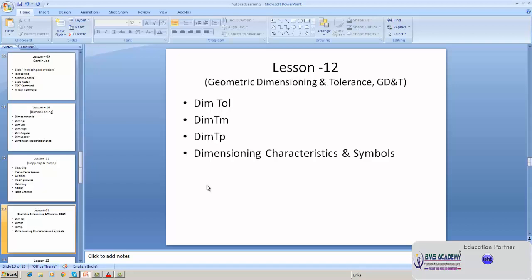design machines. It is necessary to fix tolerances on shaft diameter and bore diameter or bearing bore. This is particularly important because when a shaft is running inside a bearing bore, it should run freely, and at the same time it should not have any extra clearance.